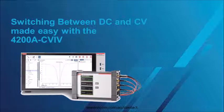Then, when, not if, but when, you need to go back and run a previous test, you need to go through all of these steps once again, just for one run of one test. And then you can never get it exactly as you had it before. Enter the 4200A CVIV. The CVIV is a multi-channel switch accessory for the new Keithley 4200A parameter analyzer that allows us to switch between DC and CV measurements while not needing to swap cables at all. Let's look at it a little deeper.